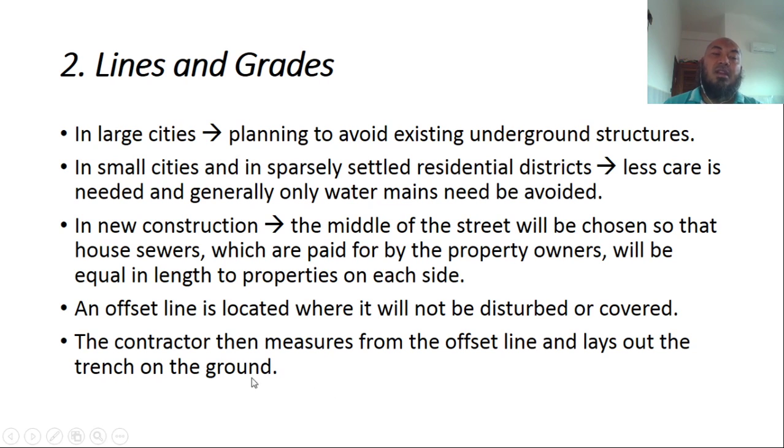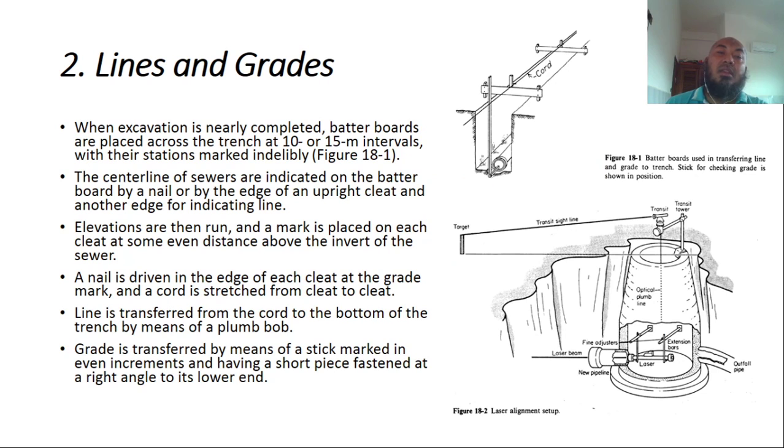So from the offset line, the contractor can lay out the trench, the dimensional trench, on the ground. And then when the excavation is nearly complete, the batter boards are placed across the trench at 10 or 15 meter intervals.